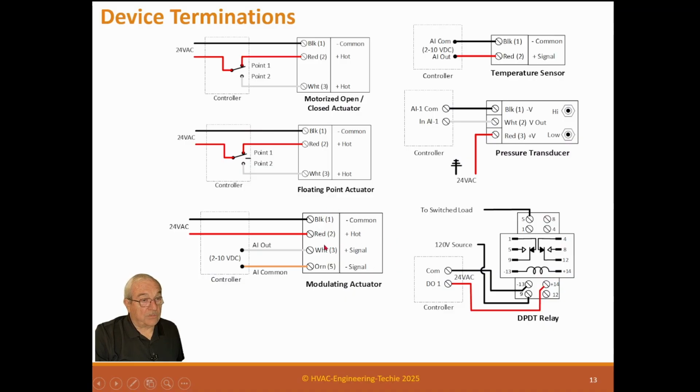Now, modulating actuators are a little different. They're still motorized, but what it does is it says, I need to be 50% open, and so this valve will drive until it's 50% open, then stop. And that's the difference between these motorized up here and this motorized modulating actuator. And that's why modulating actuators cost slightly more than a regular actuator.